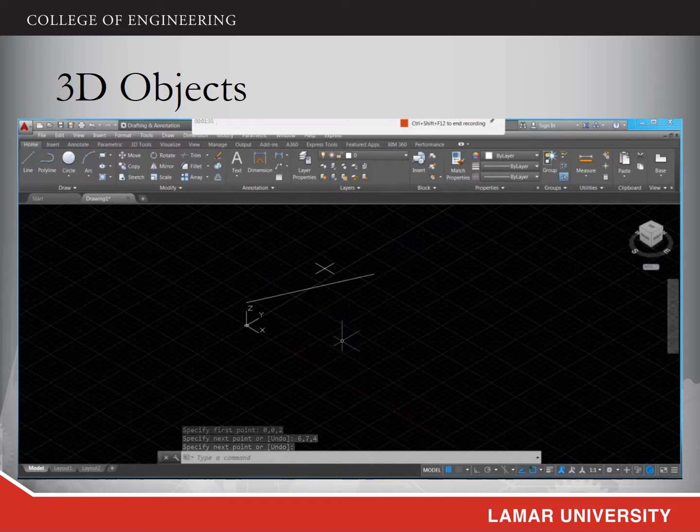If we want to generate a three-dimensional polyline, you have to call the command 3D poly. With this one, you can specify the origin of the polyline at first, say it's 5, 5, 2, and then you can specify the location of the second point, 6, 4, 1.